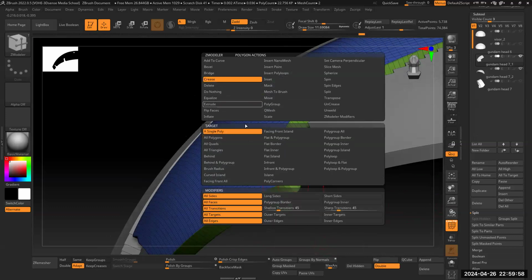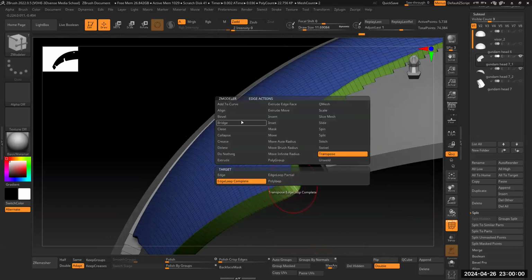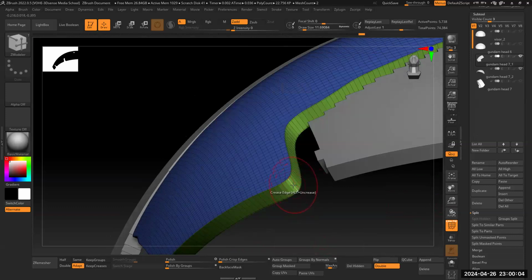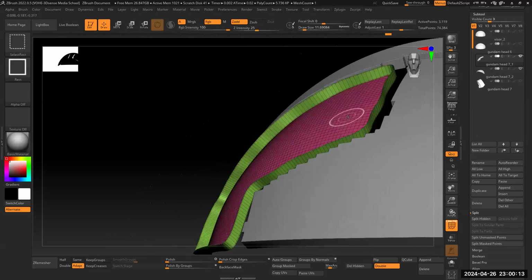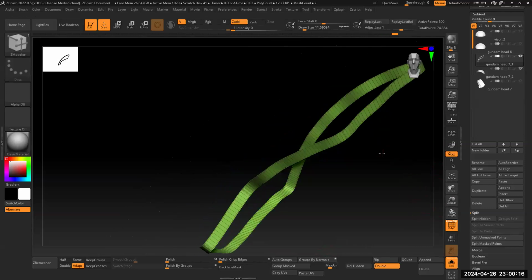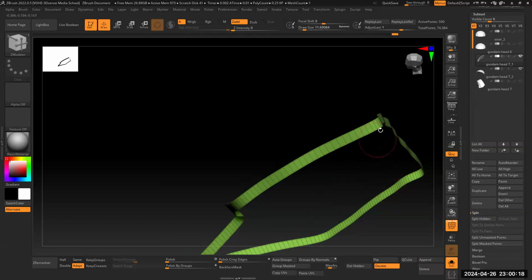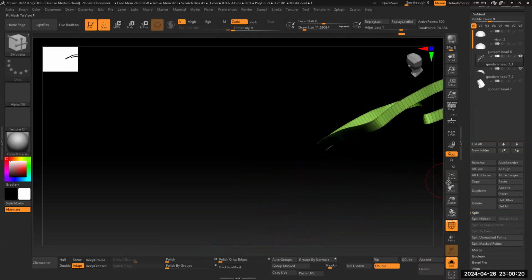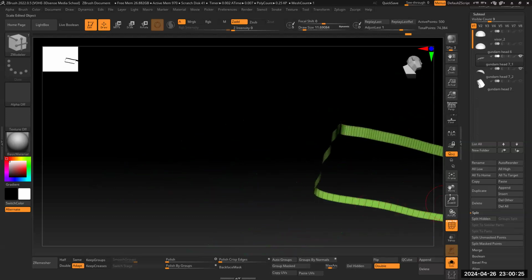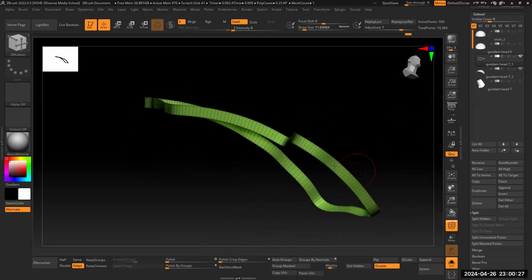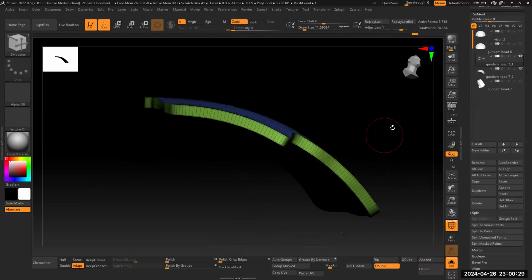So we can do the crease. Let's see, crease. We go to edge mode, right? Crease edge. So I'm going to crease one edge here, just to let it know where I want to have my hard edges. Right, you can crease here. We can just close and hide all this. We can solo this and take a look. Right, we can crease this. Crease this. Right, and crease. So everything should be creased already.